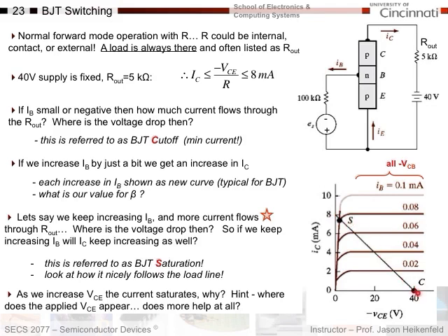You should be doing this in electronics as well. The beauty of the load line is basically using the output resistance and the voltage, I can get the cutoff point. I can get the saturation point here at 8 milliamps. I know my theoretical response for base current for this BJT, and my actual solutions for this circuit will therefore be the intersections of these. And so these will give me the values for any given base current.